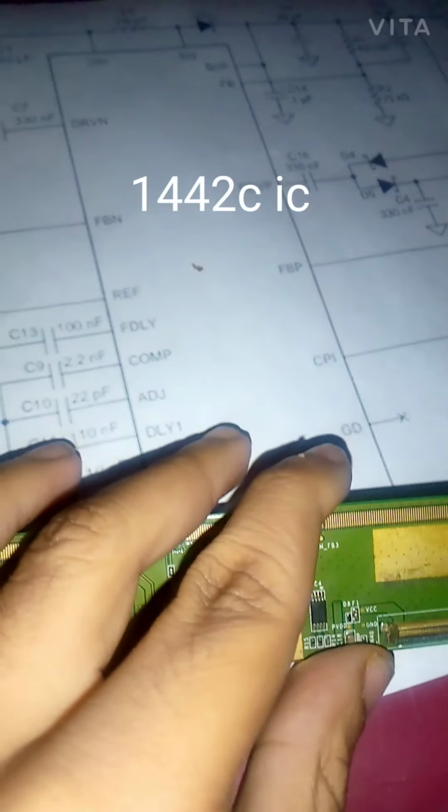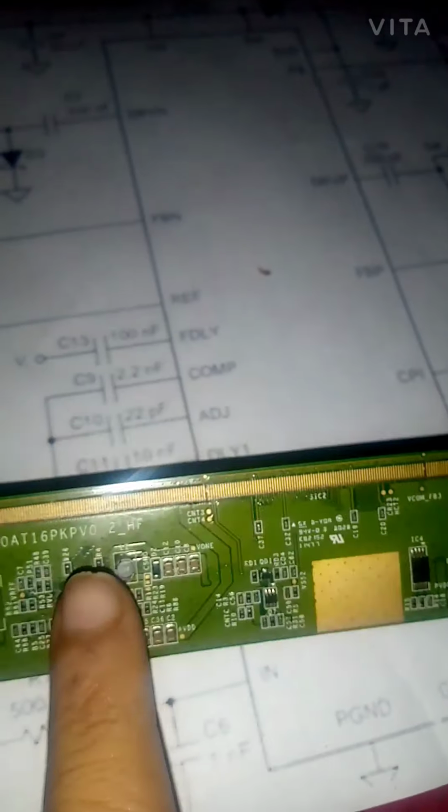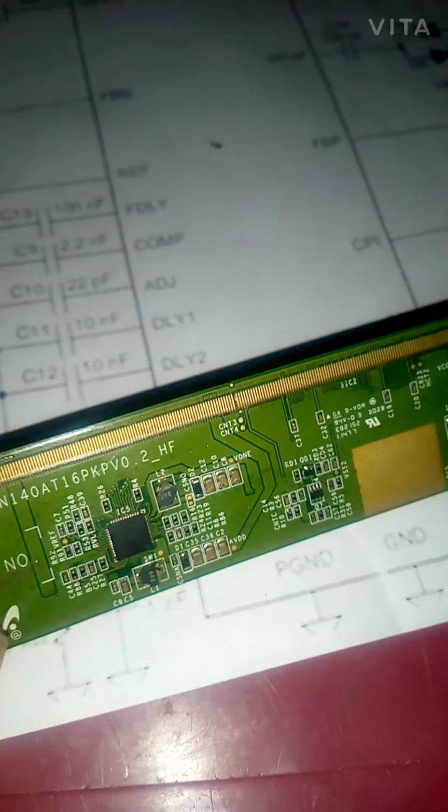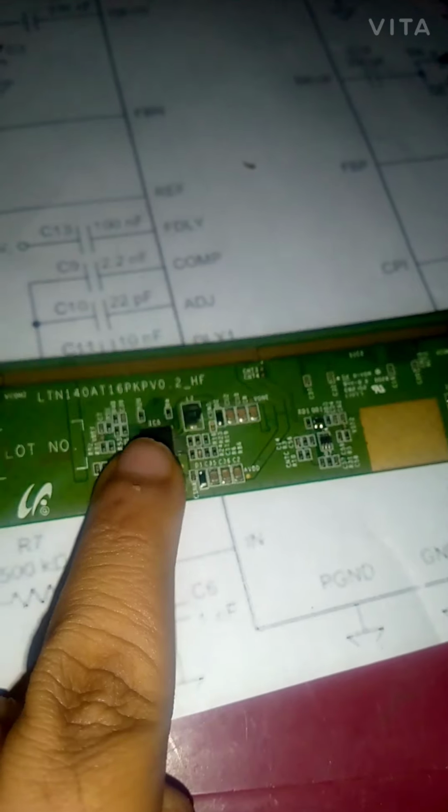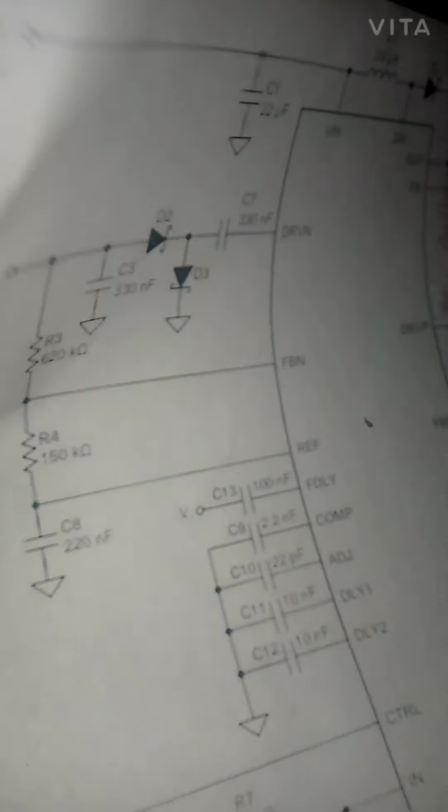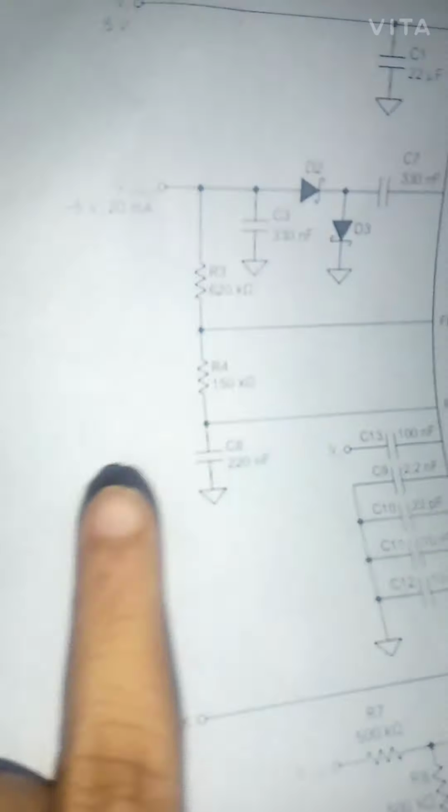So there is the same EEPROM, number 4. ROMs, and this is the main IC, which is 5112. So this is the buck regulator circuit first. The regulator needs an input of 5 volts. Panels have different voltages: 3 volt, 3.3 volt or 5 volt. In this case it is 3 volt.